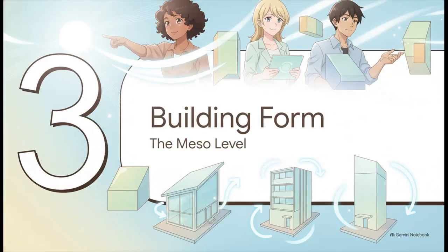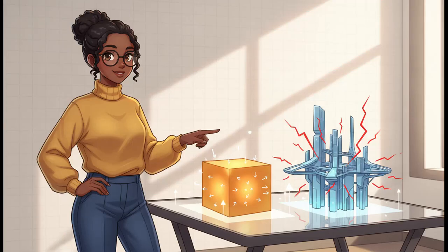Section 3, Optimizing the building form. We're entering the meso level here. So we've optimized the land. Now, what actual physical shape should the building take to maximize all these natural advantages? The most crucial thing to grasp here is the underlying mathematics of the space. The volume of air inside a building that you actually have to heat or cool is directly related to the surface area of the envelope that encloses it.